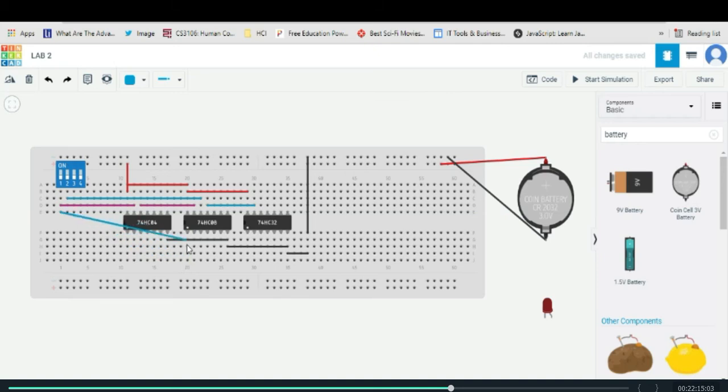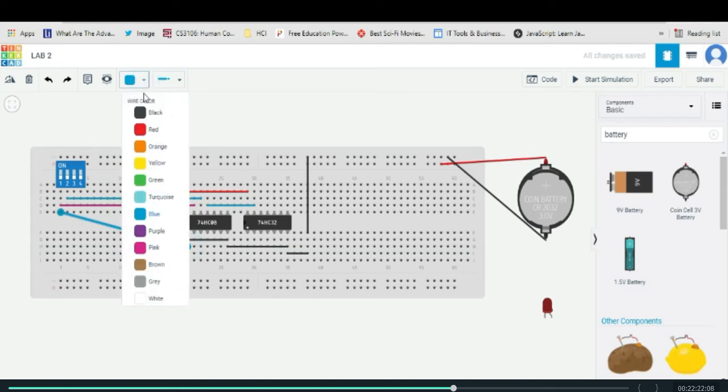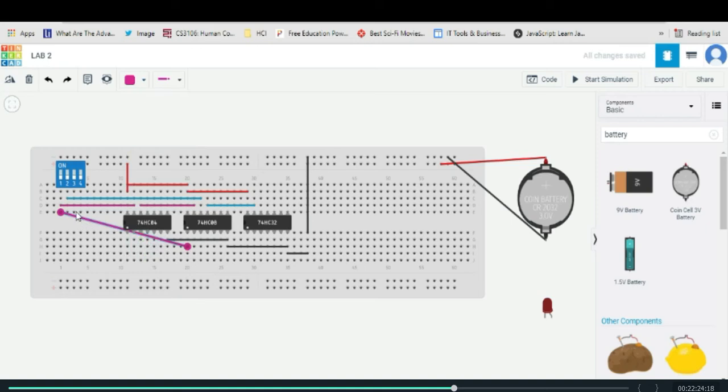This is input, right? Input pin, so we have to click it here, and then we'll change the color because it's the X, and then another is for the Y. Okay, so we have it here, Y. I intentionally did this not to overlap the wire so that you can see clearly the connection. So this is for the Y.